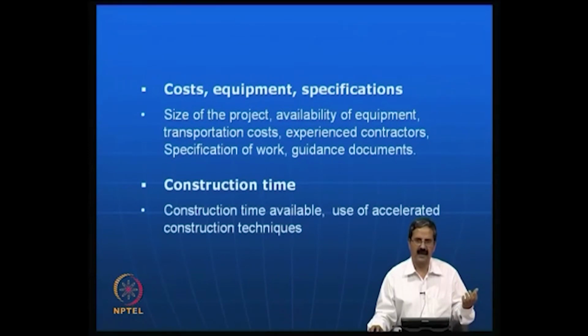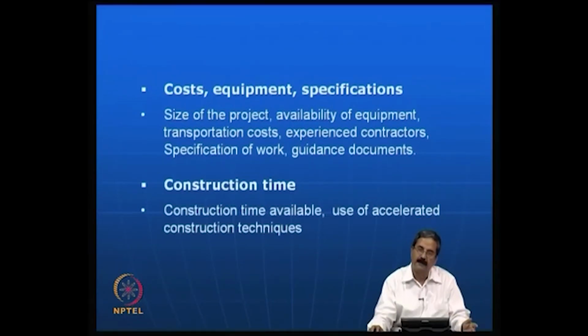You do not want to wait 8 to 9 years, you want everything in 1 year. So, you can back calculate and introduce the drainage in a proper way. Within 1 year, which is the construction time, I can finish consolidation completely rather than in 9 or 8 years. So, the construction time available should be clearly known, and the purpose also should be clearly known.